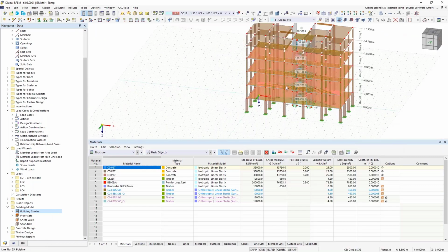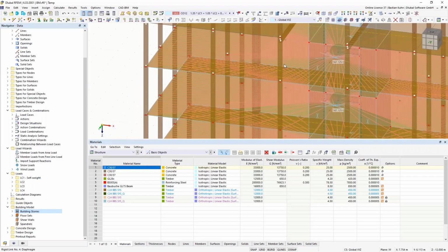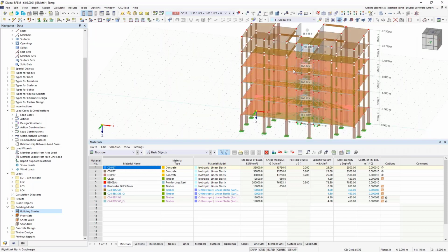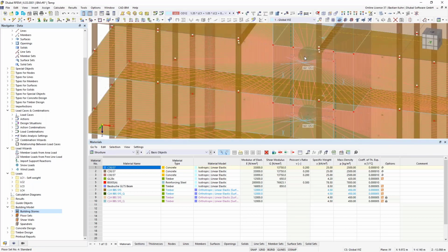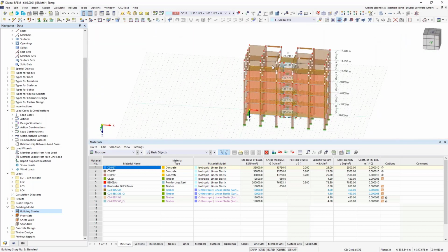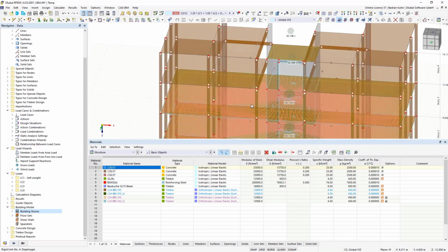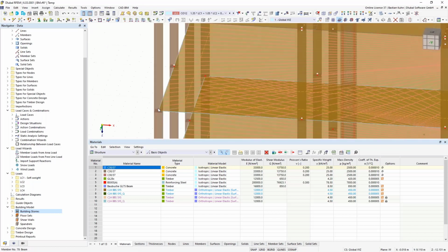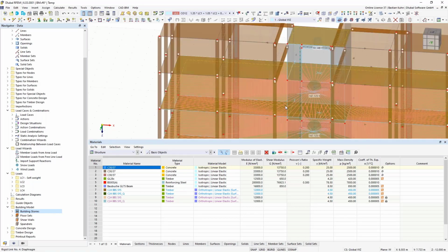And now you see here a lot of red lines. These are rigid couplings which go to a blue bubble in here. The lightest one is on the top story, 28.59 something tons. And then, okay, concrete is the heavier material, so it goes up the more down you go. These red lines, or these rigid couplings, are centered in this mass center, and they are connected to each of the columns or each FE element in each story.